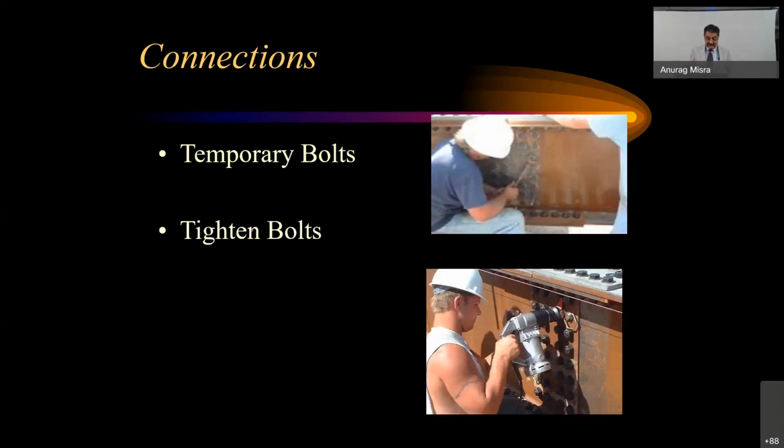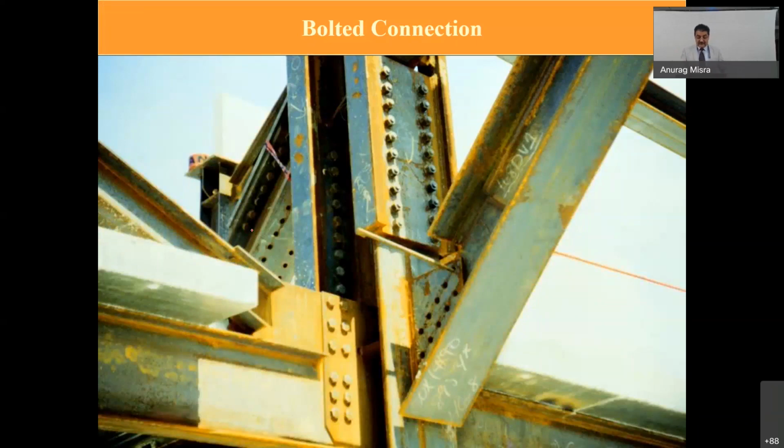All mechanical fastening is used, and it is not that we cannot create complicated connections. Wherever required, people make such connections where a large number of members are coming together. You have to be innovative about what kind of plates and inserts you leave there for making these connections.